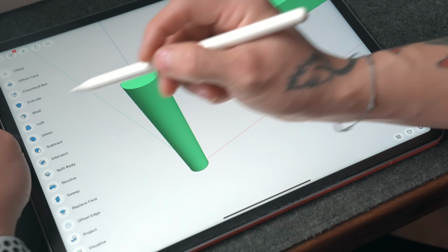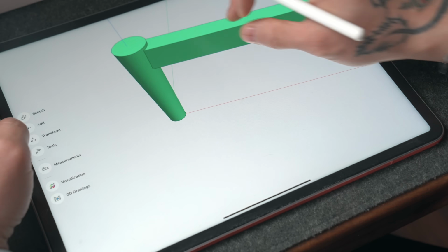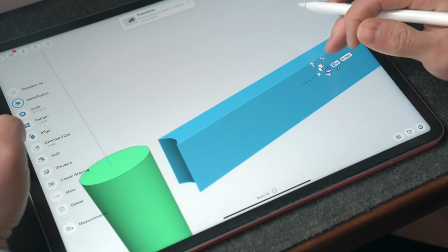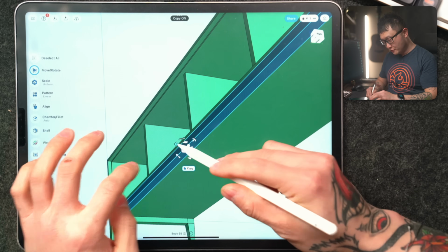I know you're probably like, okay, is that really more efficient than just extruding this part? Like, what's the big deal? Well, I know in our example it doesn't look like much, but this tool actually does more than just extending a part. So let's say that we have a circular leg that our stretcher needs to mate to. Now when we use this replace face tool, the stretcher is not only going to extend to that part, it also matches the face of that cylinder. So it's actually a few different tools mixed in one. Pretty cool, right? Okay, now let's finish this up, and we're gonna move a copy of this to the back.